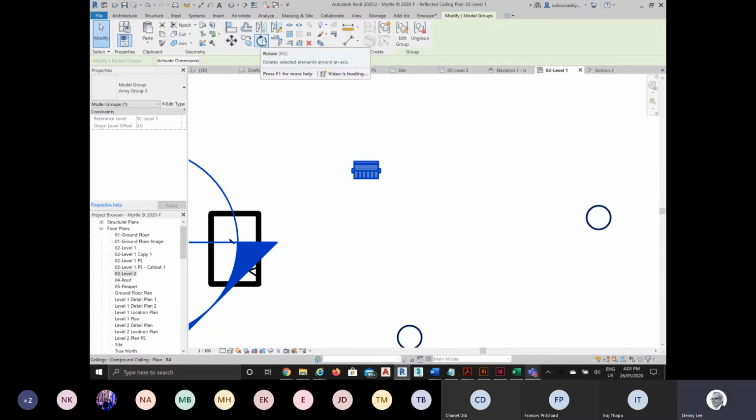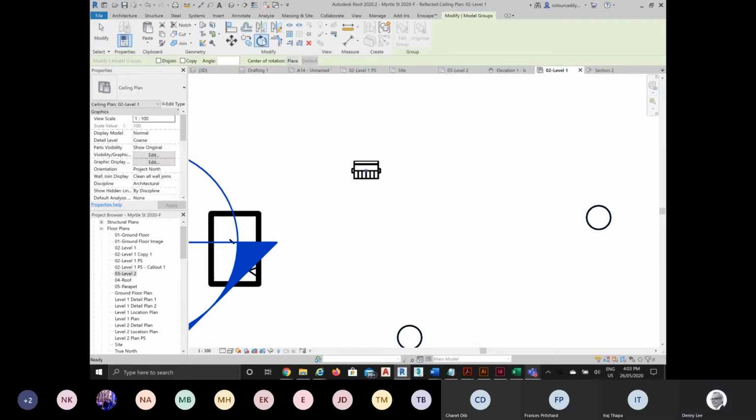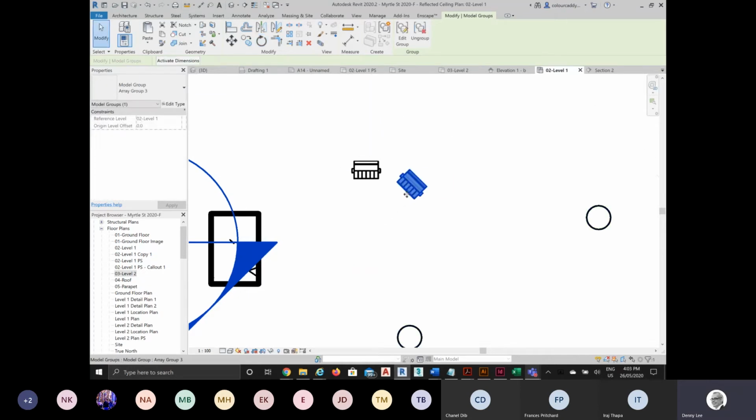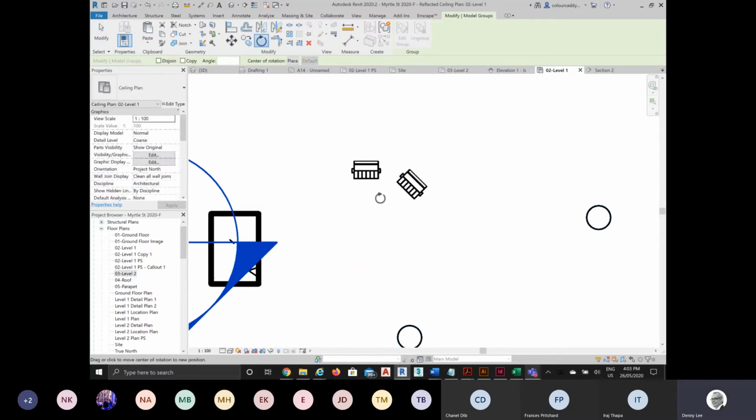And so there we can help to know that the rotate tool can be used to copy things. So there's a tick box to make it copy. So now if I rotate this, you can see there, it gives me a rotated copy and leaves the original. So that will give you all of the things that you want using the array tool. It just takes a bit longer.